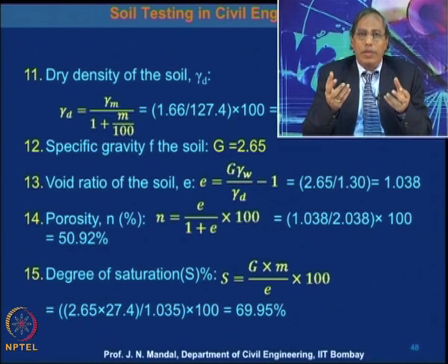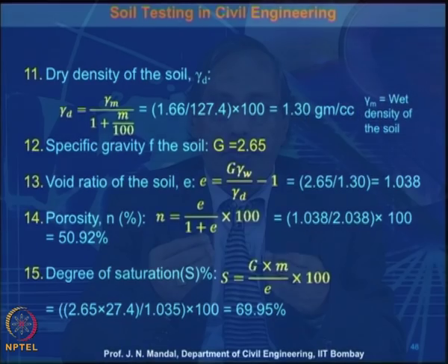So, knowing the dry density of the soil, the moist density of the soil, and the specific gravity of the soil, you can calculate the porosity, the void ratio and the degree of saturation. These are all very important parameters which one should know how to evaluate, and this will be very useful for the design of any structure which is based on the soil.